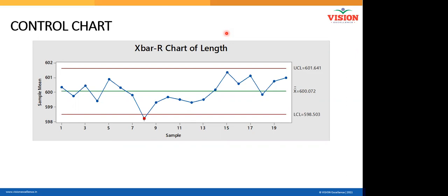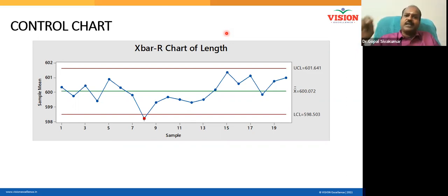If you are trying something, it is quite natural that you can miss the target, but not to the extent of 3 sigma units away from the target. If you are missing 3 sigma units away from the target, this is something telling you that the work is going on in an unprofessional way. Right? So that is why we must alert ourselves and bring the professionalism by controlling the process, by ensuring that every point is staying inside the control limit.